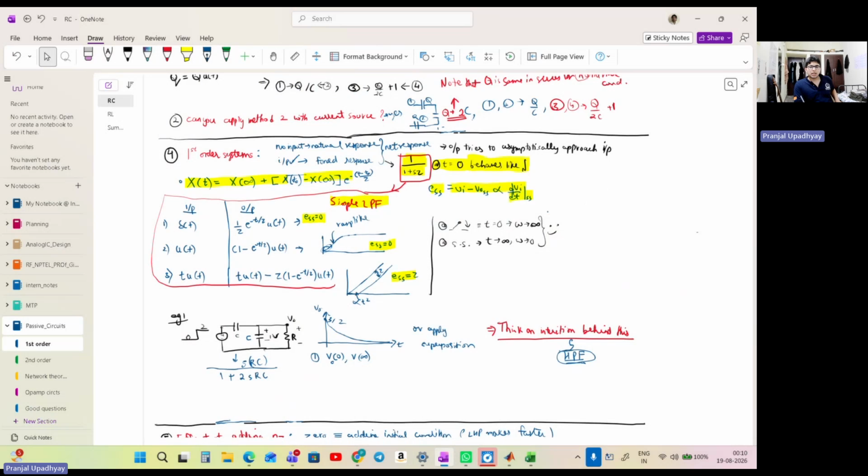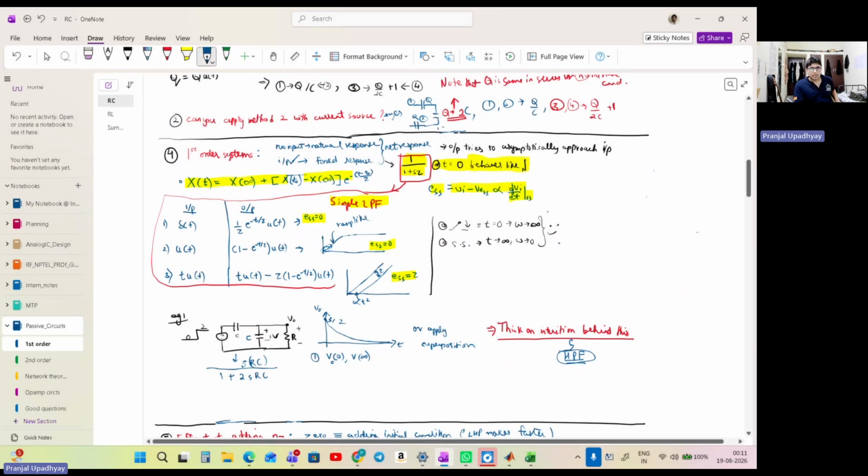And what is that other stuff? Here we just discussed a low pass filter, or low pass system. But what about a high pass system? We can actually understand a high pass system quite intuitively. If I just place a zero at the top, it becomes a high pass system because at zero frequency this will be zero, and at infinite frequencies we can just apply L'Hopital's theorem and understand that this will be a finite function, and thus this is a high pass system. We can understand it quite easily.